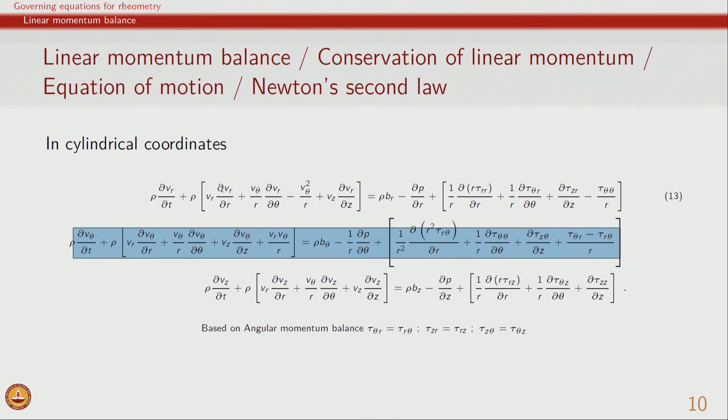And so, a fluid which is moving in theta direction, and if we are using a rheometer geometry to rotate, if we rotate it very fast, then we will have a tendency for fluid to get thrown out. So, fluid, though we are moving it in theta direction, will get a motion in r direction. So, this is very important when we do rheological analysis. We should always observe what is the status of the sample when we are doing the shearing, and very often we will be able to see that if we shear it at very high rates, the fluid actually comes out.